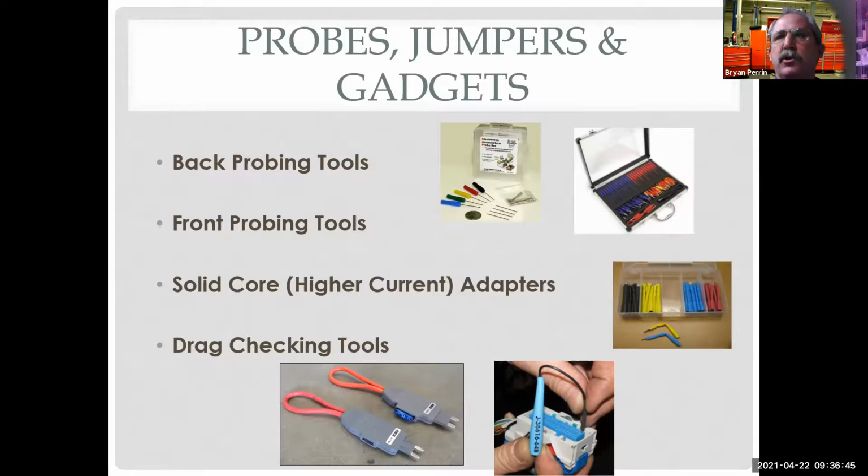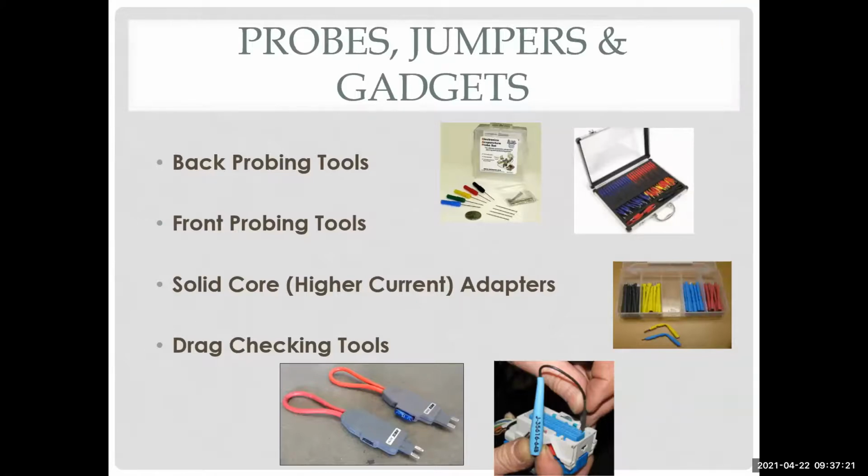And we see this a lot on newer vehicles. So one of the things we do is drag check connectors to make sure we have what's called good pin fit. We have a really positive connection. And this can happen for big connectors. It can happen for little connectors. It can happen for the diagnostic link connector you plug a scan tool in. Those connectors get worn out. It can be for the electric cooling fan. Gee, I got power and ground. I plug it in and it doesn't work. Well, voltage drop check proves it's the connector that's bad. So is there broken wires where it's soldered in the connector or crimped in the connector, or is the connector itself too loose?